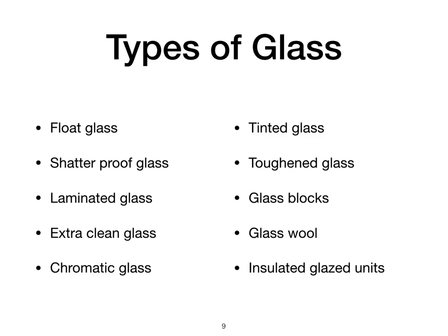Next, we'll discuss the different types of glass. First one, float glass. It is made of sodium silicate and calcium silicate, so it is also called soda lime glass. It is clear, flat, and it causes glare. They have a weight range of 6 to 36 kg per meter square. They are used as shop fronts and in public places.